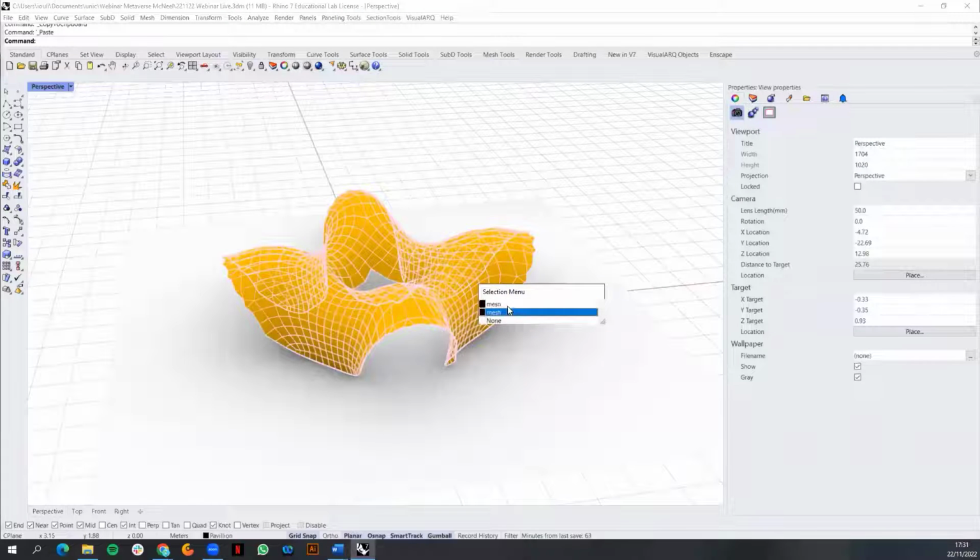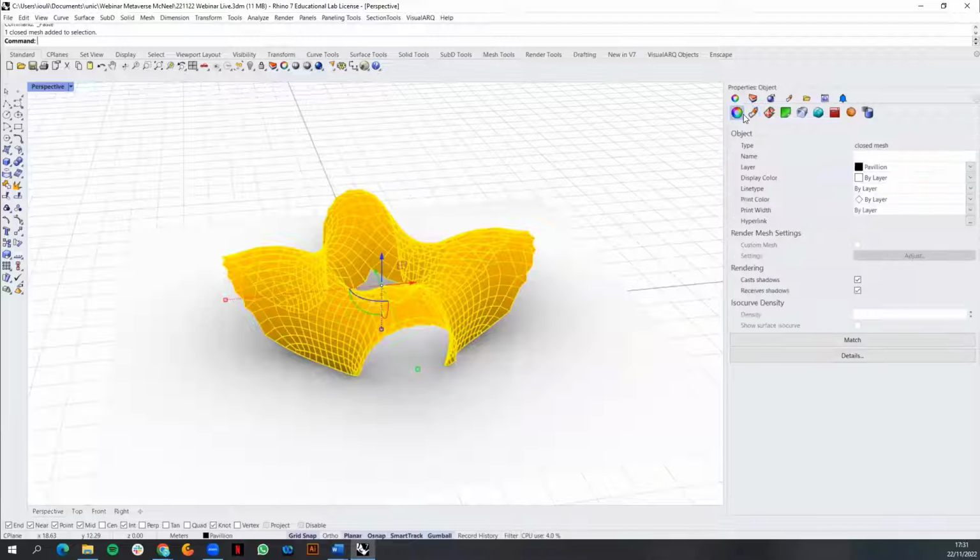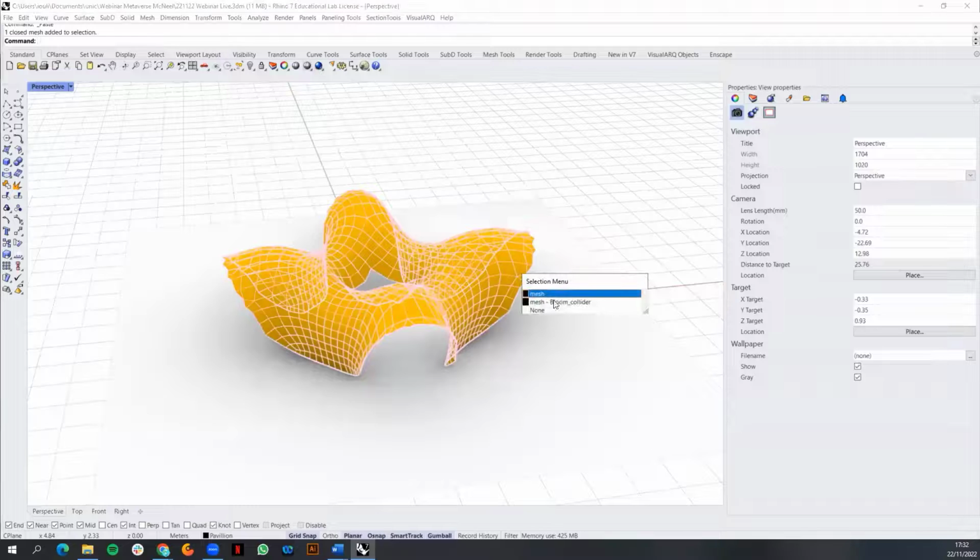And I have basically two meshes over each other, which are identical. And I have to make it a collider by changing its name. So Decentraland is basically identifying the ending of an object's name as a collider. So for example, if I call this Bloom, I have to finish it with _collider. In this way, Decentraland will recognize this geometry as a collider, and it will be also shown as invisible in the builder. So that's why the collider has to be over the other component.